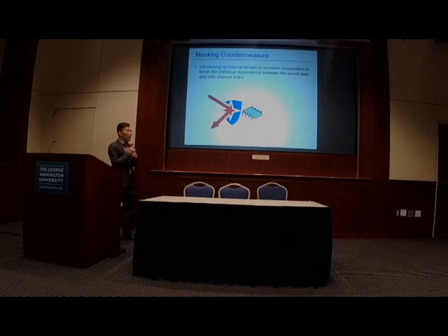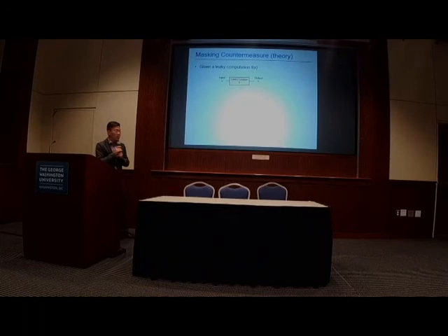It turns out for power side channels, in particular, there's some well-established theoretical foundation for doing this. One is masking. It can be traced back to information theory or secret sharing and all that. But at the code level, what you see is people introducing random bit strings to scramble the computation to break the statistical dependency between the secret data and the side channel leak. So here is a very oversimplified model.